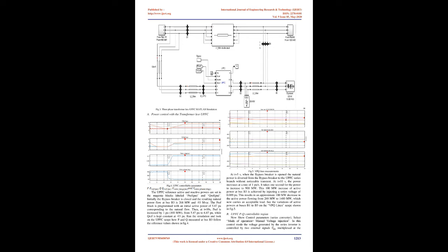Using the load flow option of the power GUI block, the model has been initialized with plants 1 and 2 generating respectively 500 MW and 1000 MW and the UPFC out of service, bypass breaker closed. The resulting power flow obtained at buses B1 to B5 is indicated by red numbers on the circuit diagram.